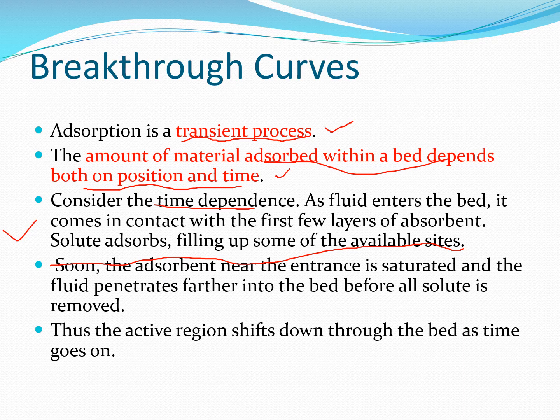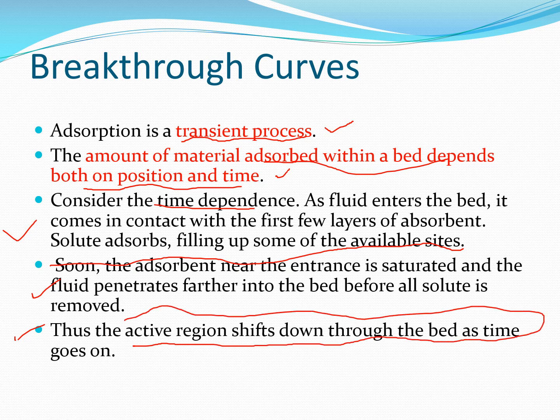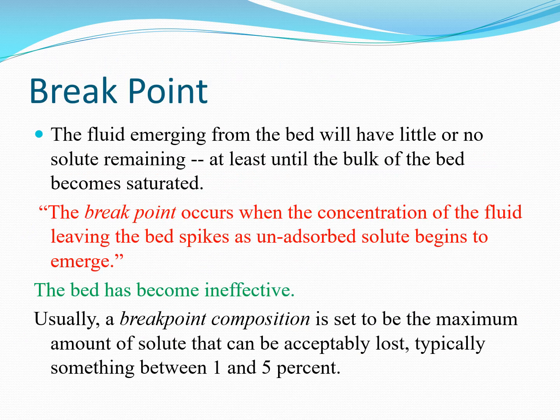Soon the adsorbent near the entrance is saturated and the fluid penetrates further into the bed before all the solute is removed. Thus the active region shifts through the bed as time goes on. This is the important point. So what's the break point? The fluid emerging from the bed will have little or no solute remaining, at least until the bulk of the bed becomes saturated.